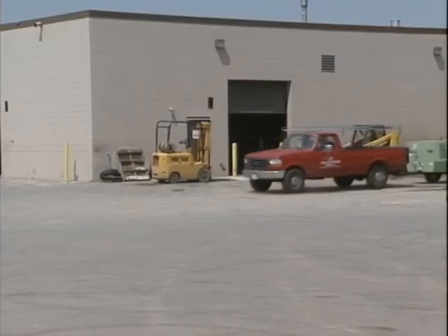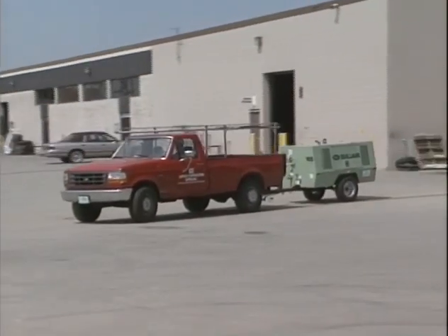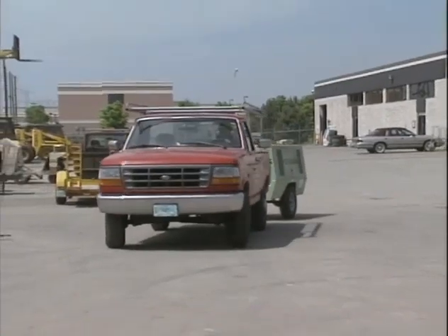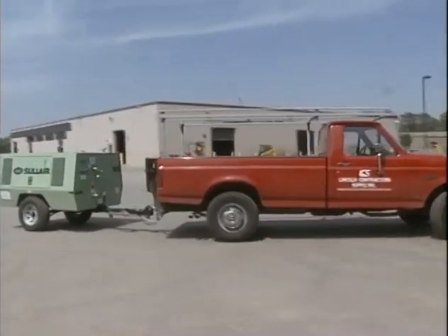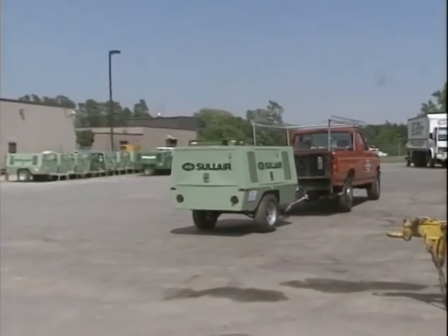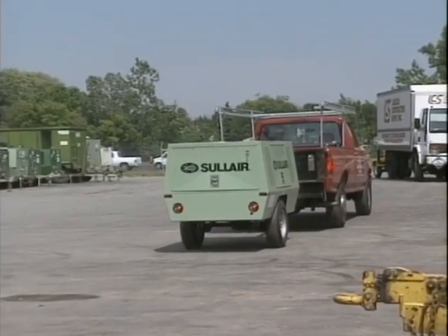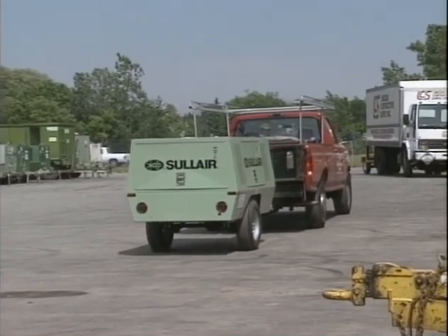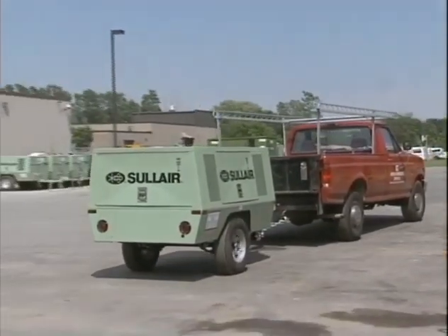Towing. Observe all local and federal traffic laws. Do not exceed legal speeds or maximum towing speeds recommended by the manufacturer. Adjust towing speed for road conditions and allow for increased stopping distances. Avoid potholes, rocks, and other obstructions and soft shoulders or unstable terrain. Maneuver carefully, especially when backing up, to stay clear of adjacent structures and avoid crimping and binding of drawbars and connections.